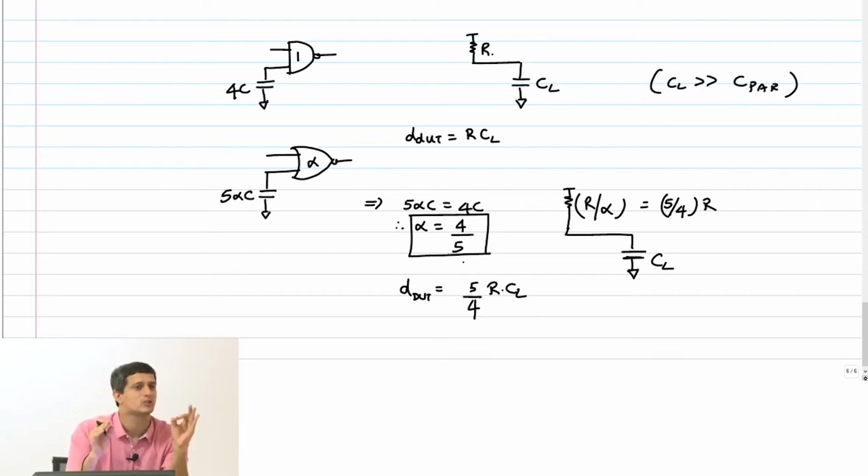One is a NAND which has two NMOS stacks, other is a NOR which has two PMOS stacks, and therefore the gate capacitance is going to be higher for a NOR gate for the same drive strength. This is one way to look at it. Or the other way to look at it, like I told you, is if I want to present the same gate capacitance to the previous stage, then the NOR will necessarily have lesser drive strength in the resistance. That is what the meaning of logical effort is. Purely because of what logic you are trying to implement, you pay a penalty in terms of how much capacitance you will offer in order to obtain a certain resistance at the output.